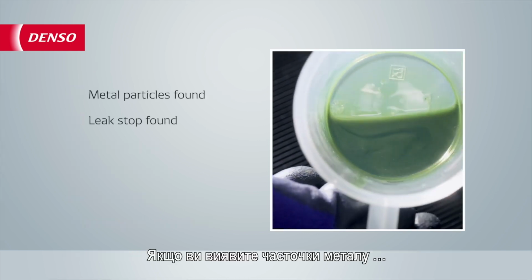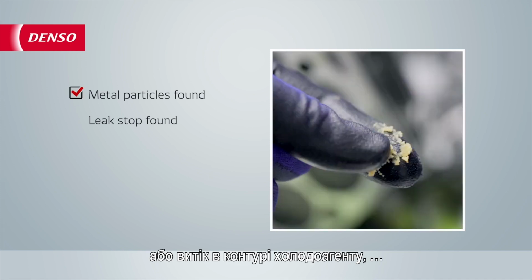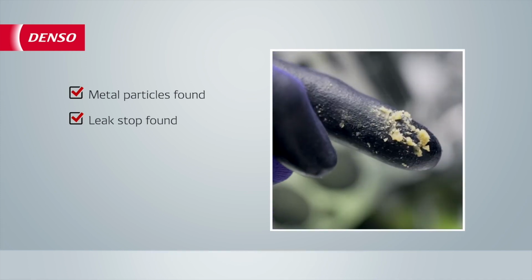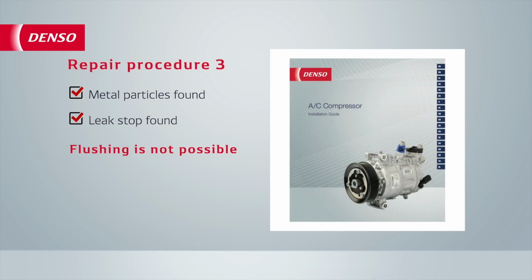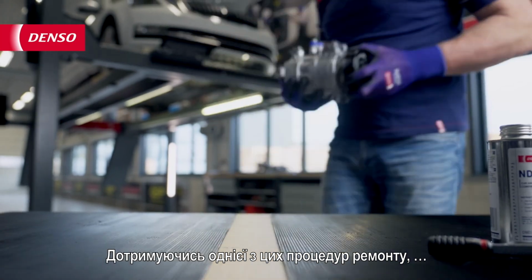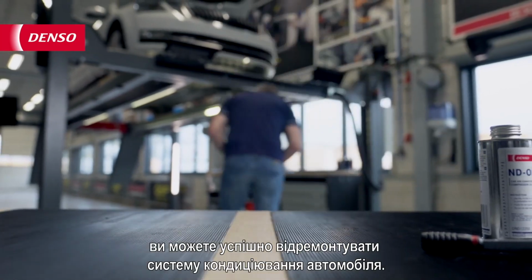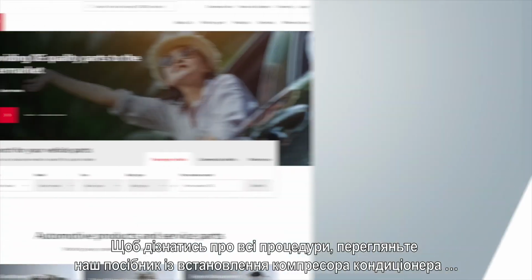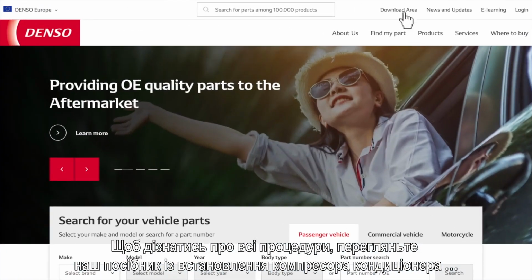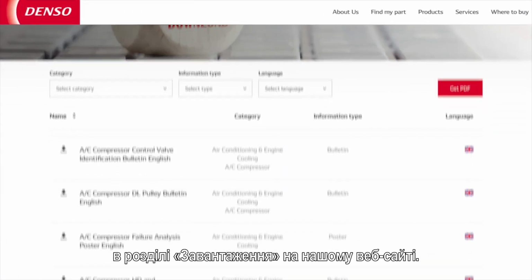If you happen to find metal particles or leak stop in the refrigerant cycle, flushing with refrigerant is not possible. You therefore have to follow repair procedure 3. By following one of these repair procedures, you can successfully repair the AC system of a car. For all procedures, check our AC compressor installation guide in the download area of our website.